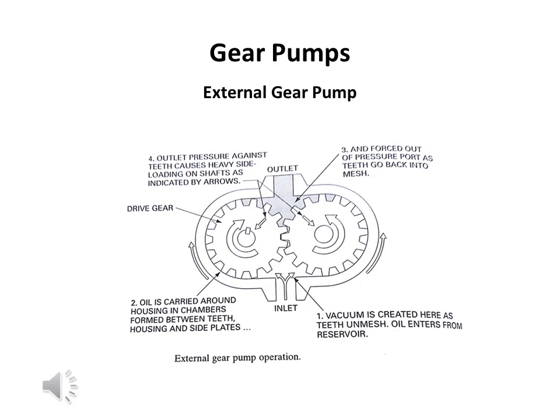Because both gears are moving away from each other, suction is created, and the oil is in the reservoir, which is under atmospheric pressure. Because of this pressure difference, the oil gets into the pump. Now the oil will be carried away because of the movement of the gear, to the top of the pump.